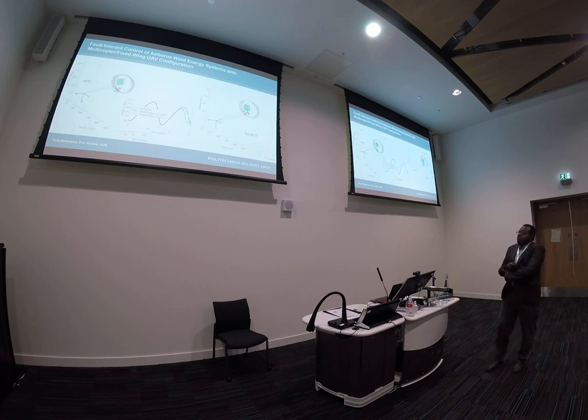So this is the trajectories of the simulation. As you see here on the right, the gray line is the normal flight trajectory without injecting any failure. But in the black line, the failure is injected somewhere in the loop. And when we don't have any active fault-tolerant control, the kite goes out of the loop.